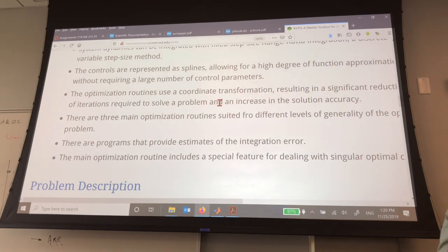There's only one shortcoming so far that I can see, and that is the delay issue. If you have a delay in the system, you probably need to use a Padé approximation to turn it into a transfer function, then use a state space. So that's the hint for you. Otherwise, everything should be very straightforward. You just go and play with it.